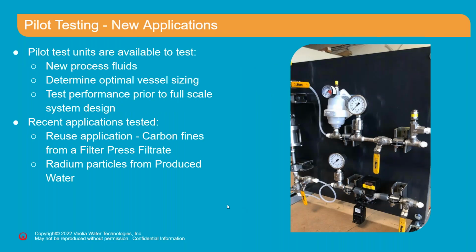And for new applications, we have pilot test units available, so we can test the effectiveness of Precoat filters for these fluids. We can also test various flux rates to determine the right vessel sizing, and we can also test performance of the filters prior to doing a full-scale system design. Recently, we did pilot testing for a reuse application to remove carbon fines from a filter press filtrate. We also did another pilot testing to remove radium from produced water.